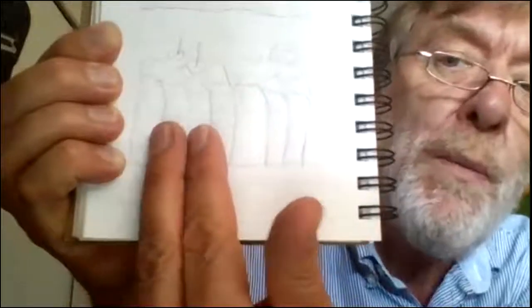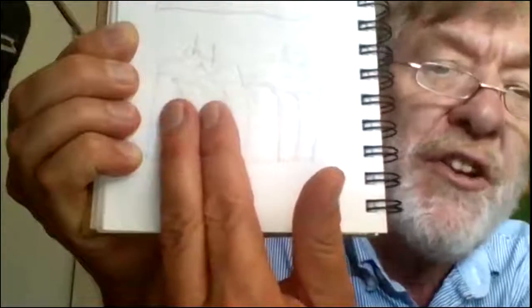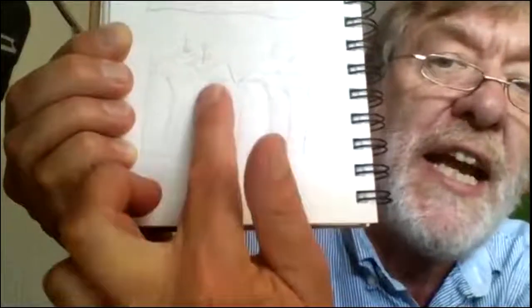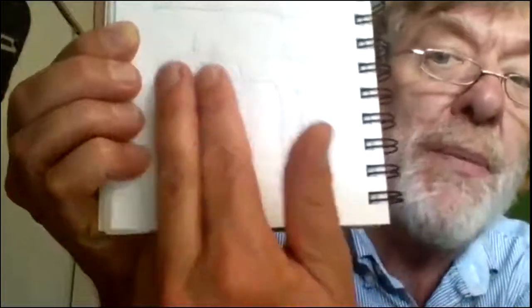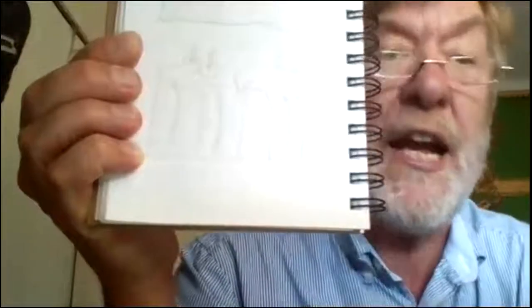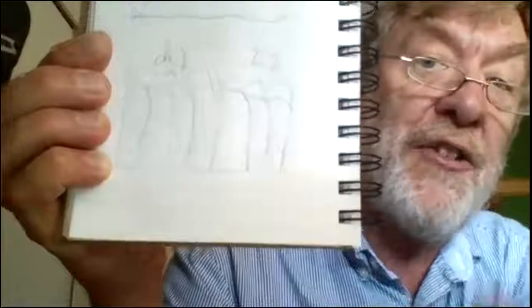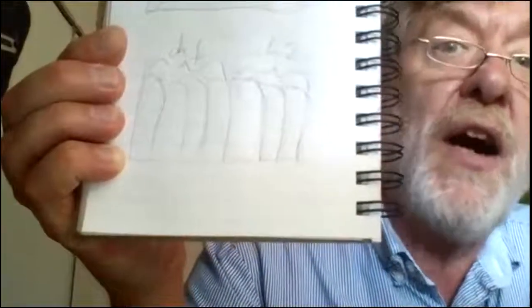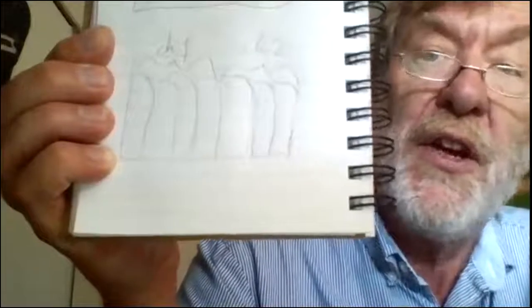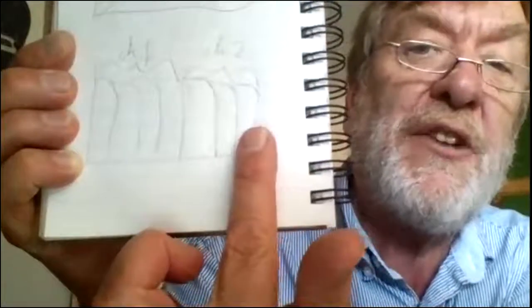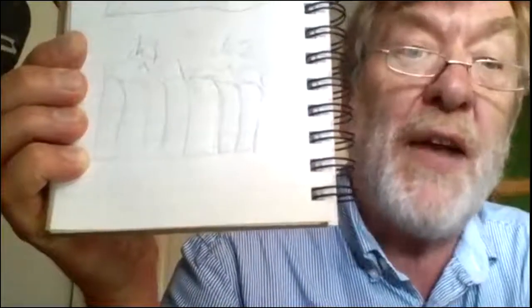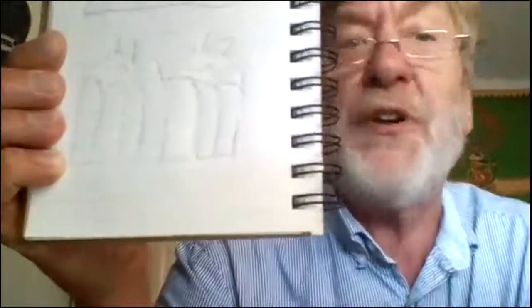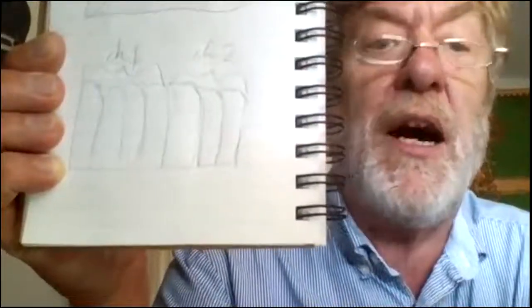So this was a group of bands that shared a digital algorithm. In each band, you could only adjust the gain, but then they could lump together to produce a channel where stuff other than gain could be adjusted. And then channel 2 was the collection of the highest frequency 3 channels. So the gain was individually adjustable in each band, and then they were also lumped together as channel 2 when they shared a different kind of behavior, where you could adjust something other than just the gain in those 3 channels. Okay? Anyway, just to kind of highlight the difference between band and channels.